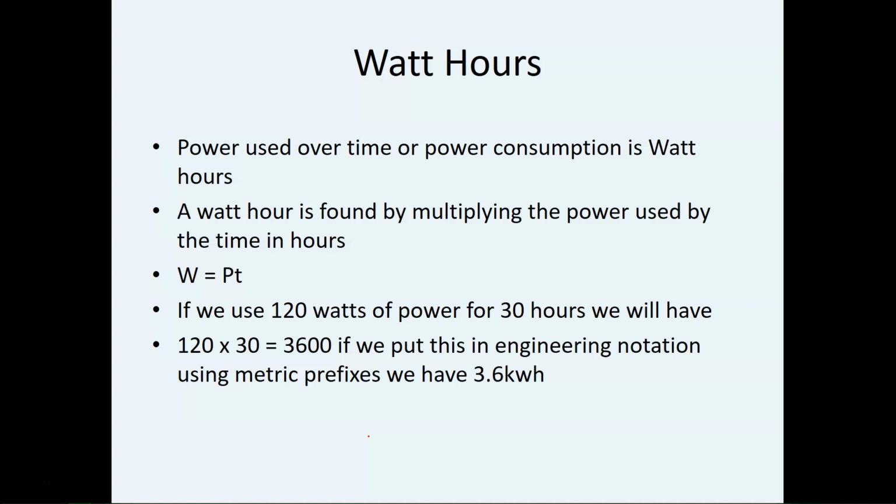You can literally go through different appliances, find out how much wattage they're using, and you can calculate your power bill by doing this. So let's say you look at a lamp and it's got a 50-watt light bulb. How long do you leave that lamp on daily? How many days in the month have you left it on like that?